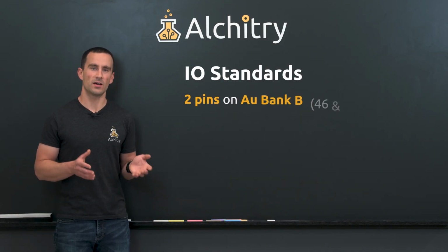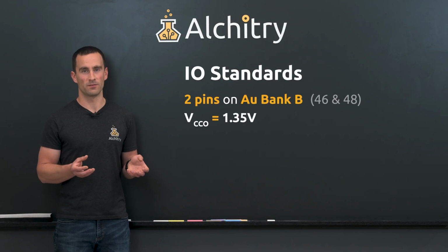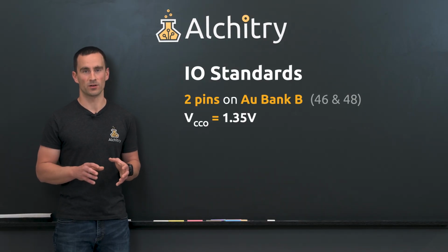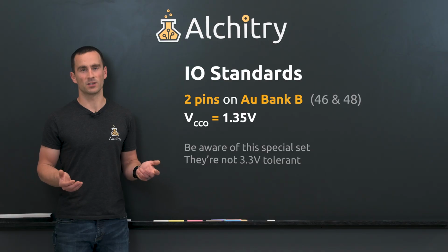2 pins on the AU have their VCCO fixed at 1.35 volts. These are extra pins from the group used to connect to the RAM on the board. Just be aware of this special set when designing your pinouts, as they are not 3.3 volt tolerant.